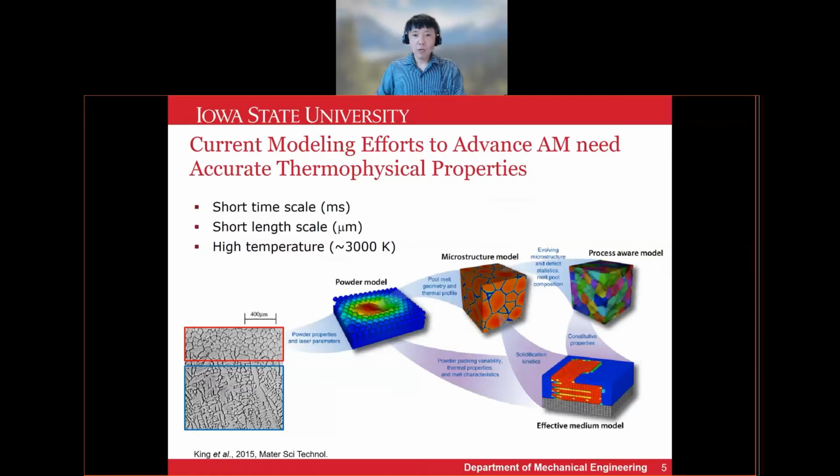We observed that the convection in the melt significantly altered the solidification behavior and its resulting microstructure, as we can see from the figure on the left. In this figure, the upper and lower regions underwent different phase selection processes during solidification and had quite different grain structures.